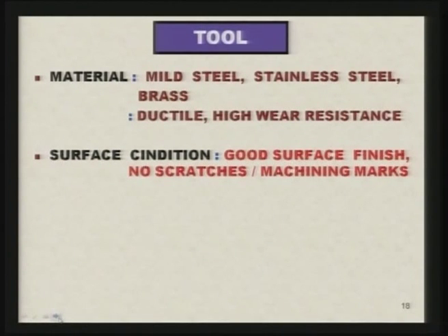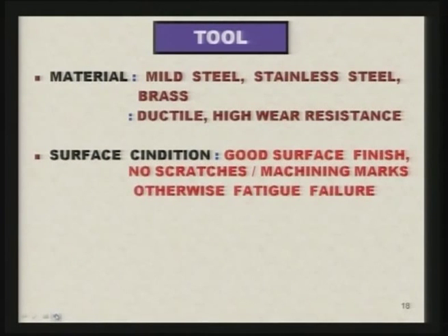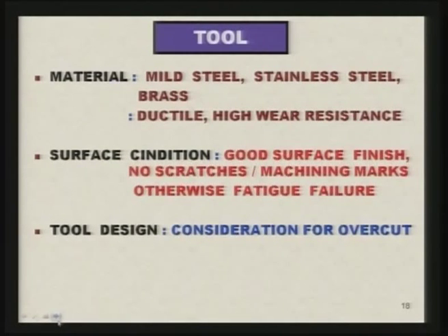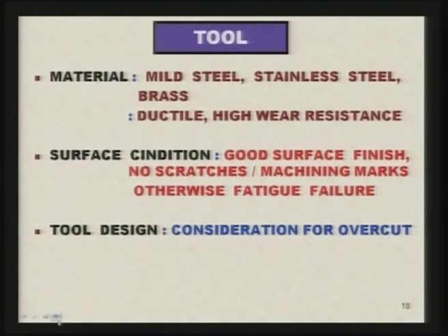There should be no scratches or machining marks on the tool, otherwise they will be reflected on the workpiece, as well as fatigue failure of the tool will take place, because the tool is subjected to very high frequency changing load. So, fatigue failure of the tool may take place if it has certain scratches or machining marks left over there.